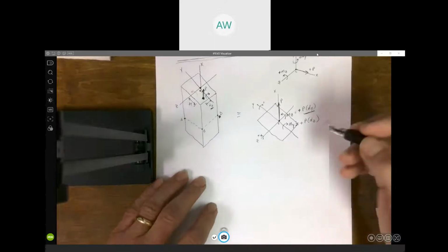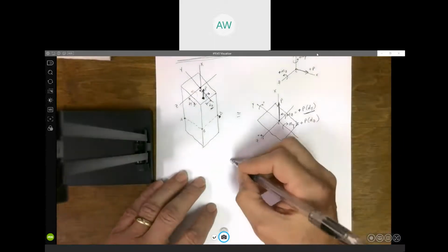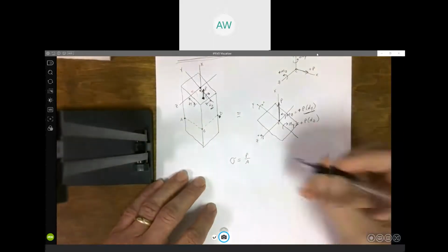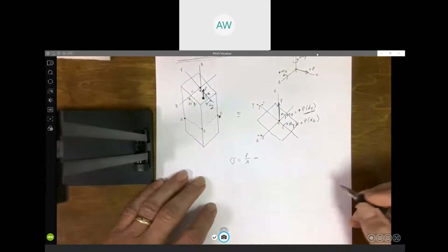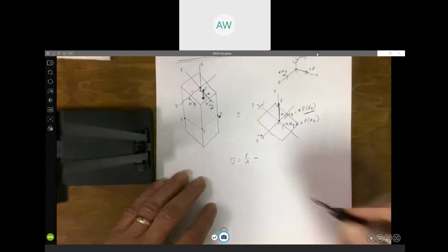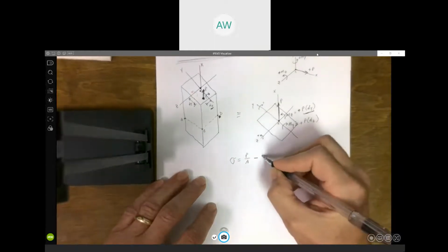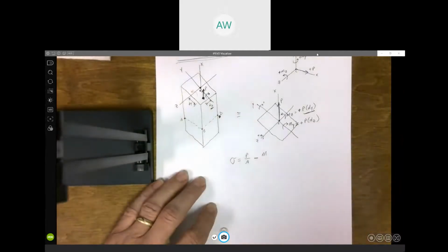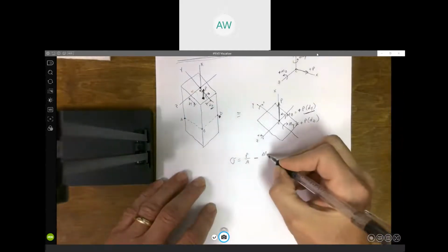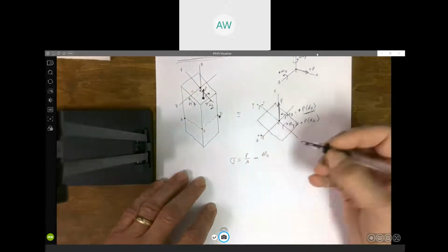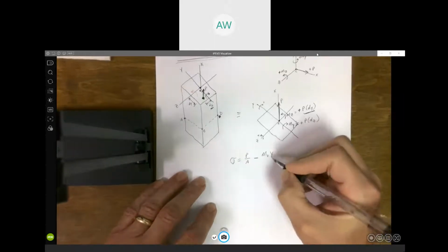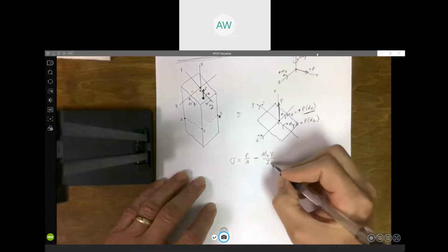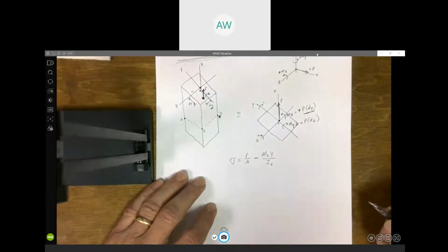So we wind up with an axial load and moments about both the y and the z-axis. So when we calculate our normal stress, we've got the same formula that we had yesterday, P over A minus Mz y over Iz. But here I'm going to specifically differentiate, since now we've got moments about the z and the y. What we did yesterday was the moment about the z times the distance y away from the z-axis, divided by Iz.